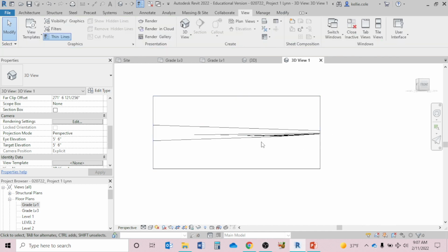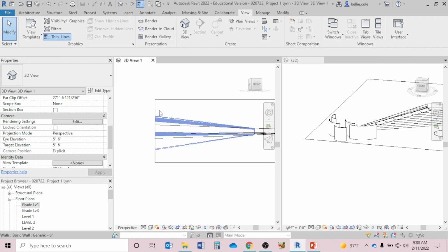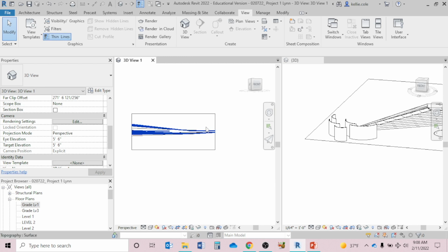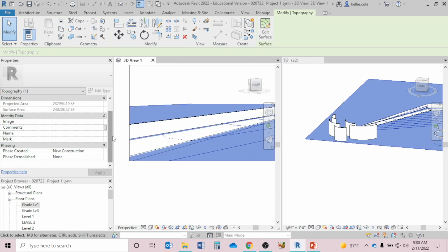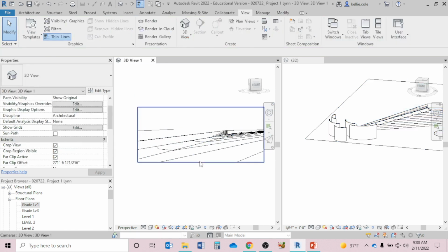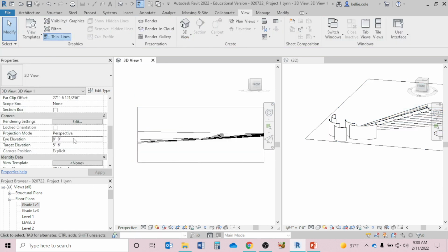So what is it that I'm exactly seeing here? Why don't I close some tabs and do my wall tile? So when I select this object, I see that I was actually positioned below grade. I can hold Shift and adjust my view accordingly. 9 foot actually would be at grade level.